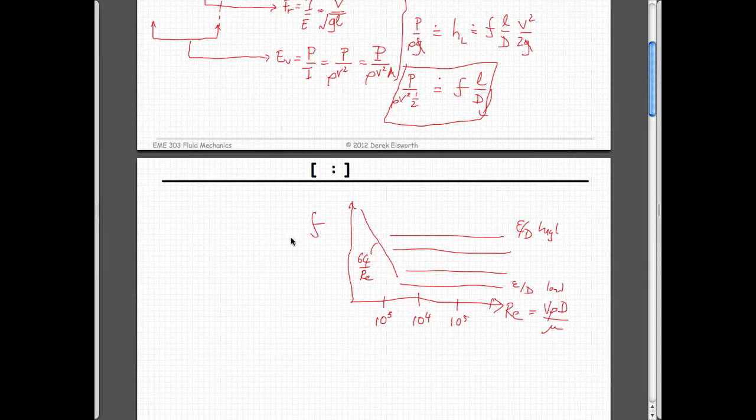So friction factor, if you think about it, well, we can multiply by some constant, whatever that is. We're saying that this is equal to a pressure divided by a half rho v squared. This is an Euler number, right? What we've called our Euler number. And so all it serves to define is the fact that there's a direct correspondence between internal and external flows. It's just that we're interested in different things. In internal flows, we're typically interested in how much fluid you can push down this pipe, and we want to know what the frictional resistance is to be able to modify our equations to calculate that.